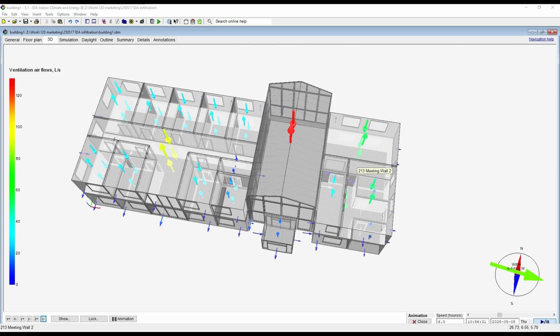In the real world, infiltration is coupled with other categories of ventilation, such as opening windows or HVAC. Infiltration is affected by pressures generated from HVAC. So let's model that. We can do a 10% oversupply and some localised extract. Both of these, the oversupply and the extract, are trivial situations in HVAC. They are ubiquitous, but they're not trivial to model, except in IES. So let's do it. First of all, let's model this 10% oversupply, and then we can model the extract.